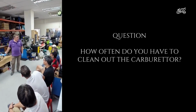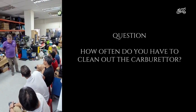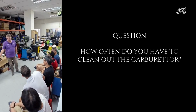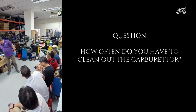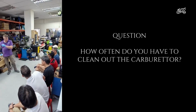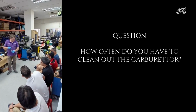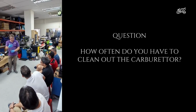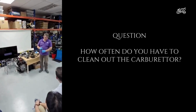I wouldn't touch it until there's a reason to. So in terms of service, just change the air filter. Yeah. So I wouldn't really go in. On these SUs, you need to top up this dashpot. There's some oil in that tube in the top, so you need to make sure that the oil is topped up, and you need to make sure the air filter's in good condition. But other than that, I really wouldn't touch it.